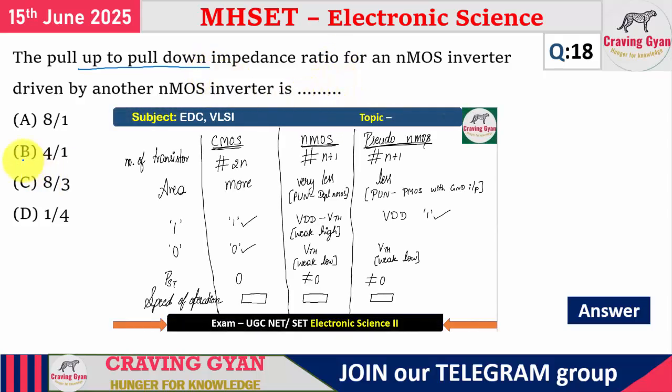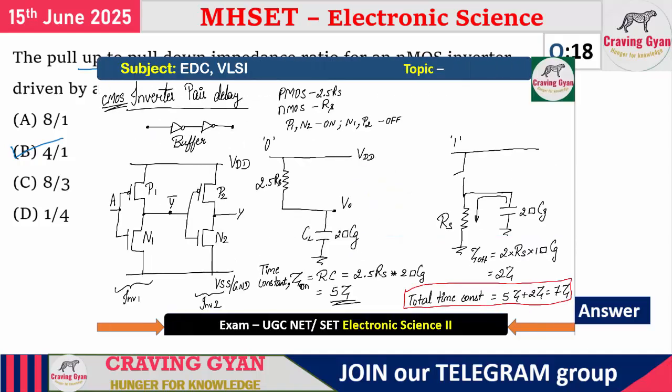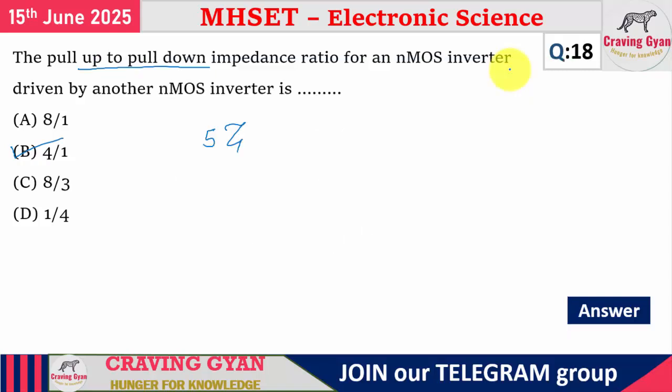In the 18th question, what should be the ratio of the pull up network to the pull down network? It should be 4:1. So the overall delay, in the case of NMOS pair delay, you are going to get 5 tau. That will be 4 tau plus tau, or 1 tau plus 4 tau. That will be 5 tau you are going to get. In the case of CMOS delay, it will be 5 tau plus 2 tau, or 2 tau plus 5 tau, 7 tau. Right? So the NMOS inverter pair delay is less when compared to CMOS. In the case of NMOS, delay will be 5 tau, and in the case of CMOS, delay will be 7 tau. For the 18th question, option B is going to follow.